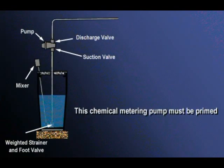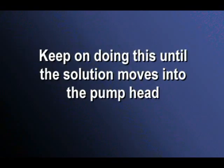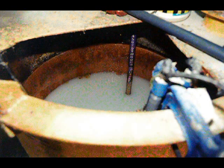If the pump is located above the supply tank, priming may be required. Without lifting the foot valve out of the solution, move it up and down quickly. This will make the foot valve lift and will force liquid into the suction pipe. Keep on doing this until the solution moves into the pump head. When the pump head is filled and the solution has reached the discharge valve, the pump is ready to start pumping. Be sure that there is enough solution in the tank before the pump is started.